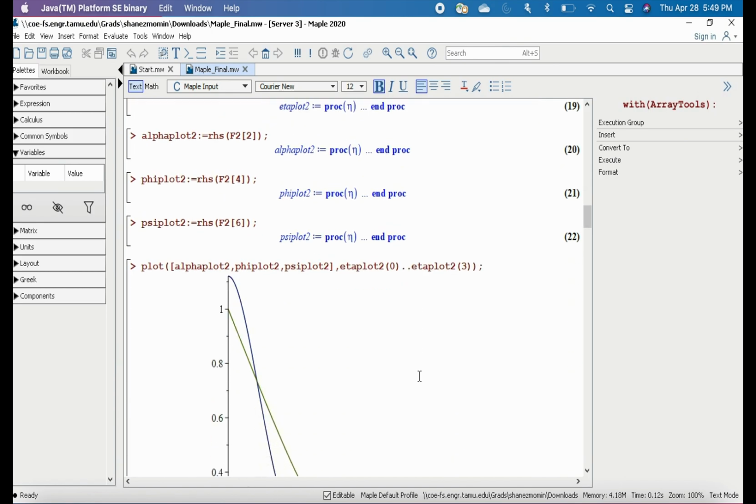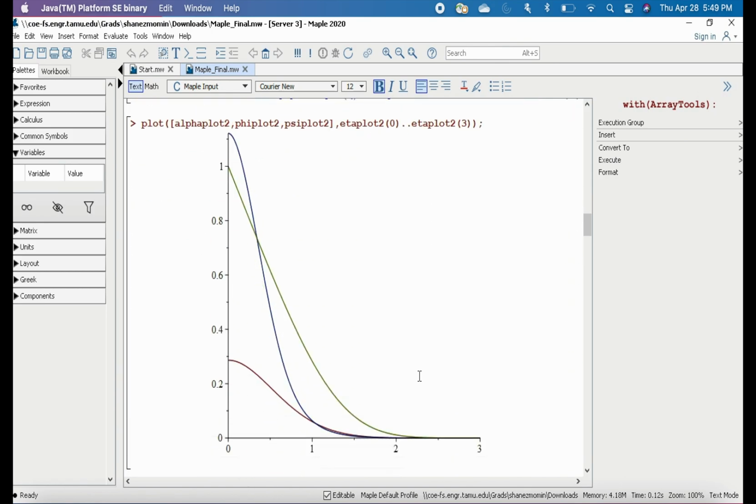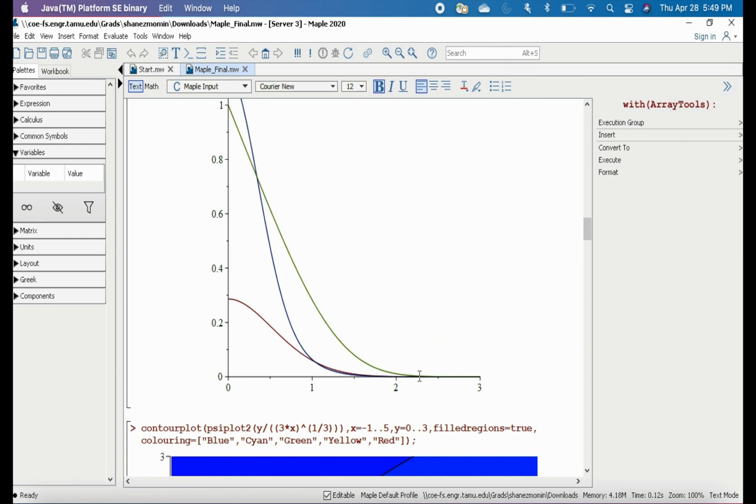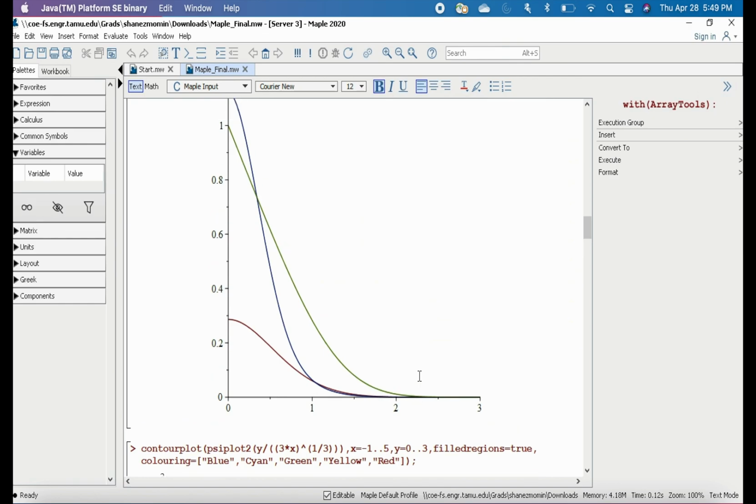And as we can see from the plot, the intermediate concentration starts at a higher value because of the change in diffusivity. This means there will be more intermediate at the surface compared to the bulk. We also observe that the intermediate concentration falls below the product concentration near an eta value of 1, as described in the original paper.